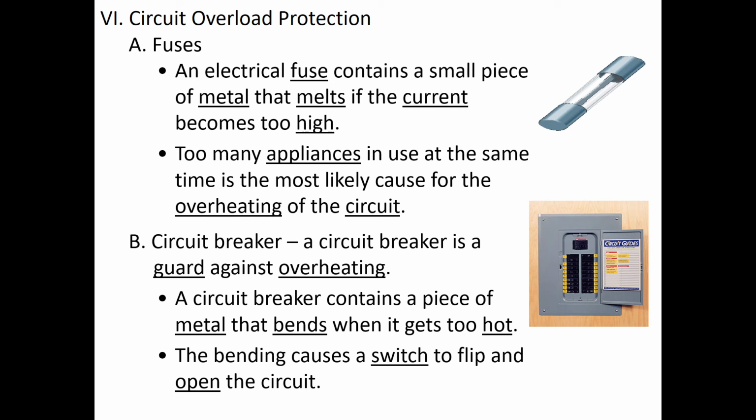If a fuse were to trip, you have to replace the fuse. But we can build it quite small, so small devices like calculators and voltmeters that will be handling lots of current usually just have a fuse in them. When it breaks, we just have to replace it. Your house, though, if you hook too many things up to the same outlet, it can trip the breaker, and it allows you to go in and reset it. If the breaker were to fail, your house could catch on fire if too much current goes through the same outlet.